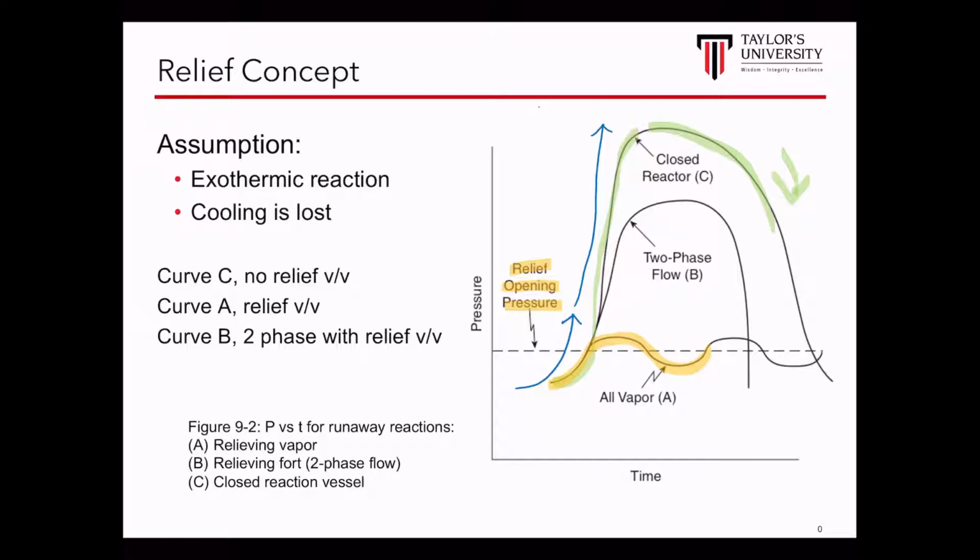And the moment it hits this particular red line here, it will continue to just run in such a way. So you don't have a sudden release, or you don't have to wait until the chemicals are fully closed. And also, the moment we have this relief system in place, we will also get to know that there is something wrong with our system.